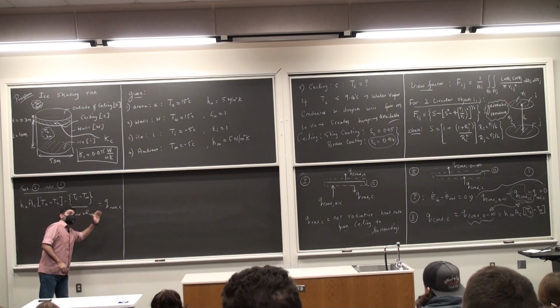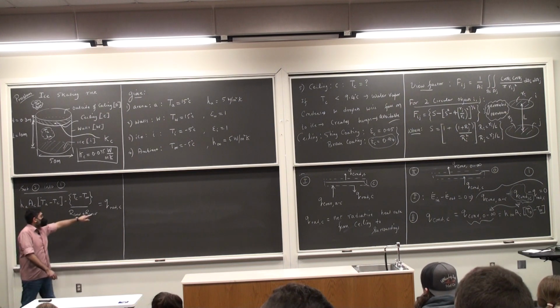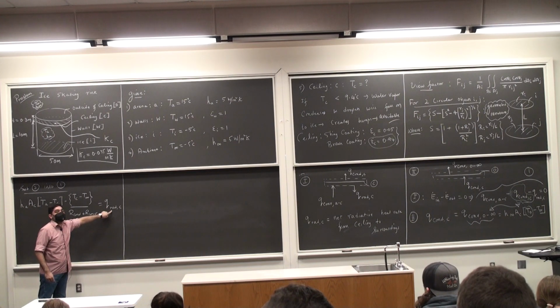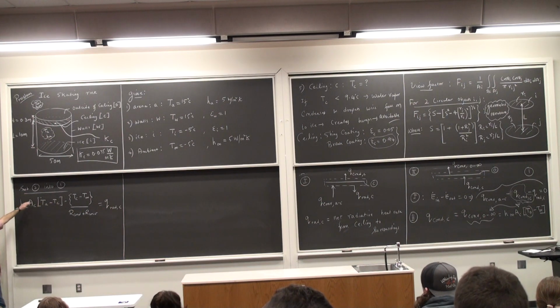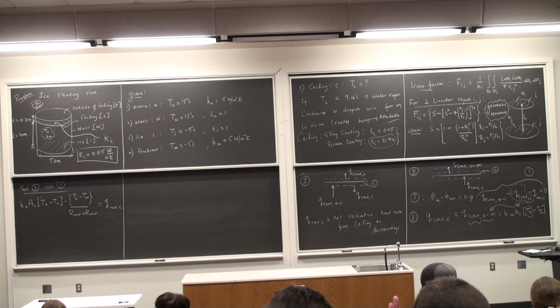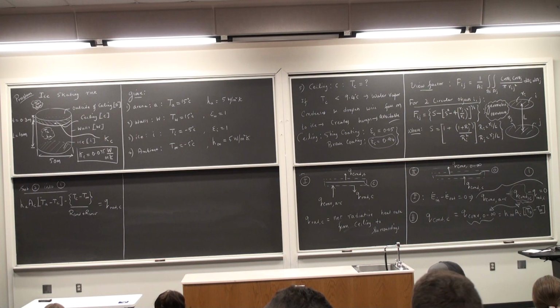So to isolate this term, we are doing all of these things, and it is obvious that this will end up being a function of the temperature of the ceiling. So this is my first equation where Q radiation is a function of Tc. I will have to come up with another equation where Q radiation is a function of Tc. With 2 equations, I can equate them to solve for Tc. I should get something that is algebraic and highly nonlinear, Tc to the power 4 and all other things going on. I have the values for these things.